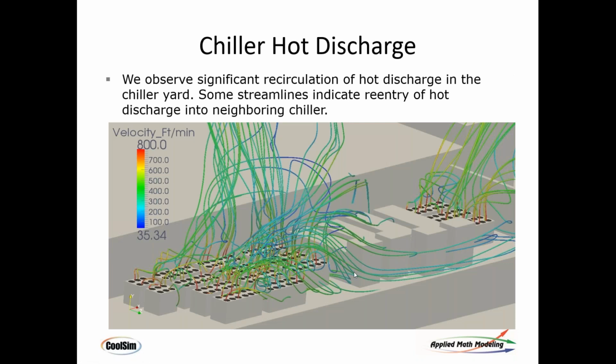Here is some of the output that we get out of these kinds of runs. These are what we call path lines. Path lines are simulated particles in space, so we're just simulating the path. In CFD, you can artificially put these in, and we call them seed points. The number of seed points here, I think, looks like we have 1 seed point per output, maybe 2. And what you can do is track them through air. Because we have modeled every single polygon that represents the air, we can actually see what's going on. And this is the power of computational fluid dynamics. It gives you the visual ability to look at the airflow and understand what's happening. It makes the invisible visible. And this is very important when you're trying to understand it.